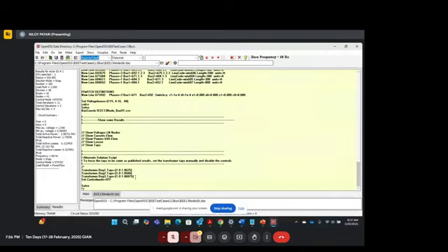Because once the taps are fixed, we are saying that we are boosting the voltages by the same amount as was done in the docx file, right? So then the OpenDSS results and the IEEE test results that you see in the document file should be exactly the same. If they're not the same, that means there is an anomaly, there is a problem in your own models.